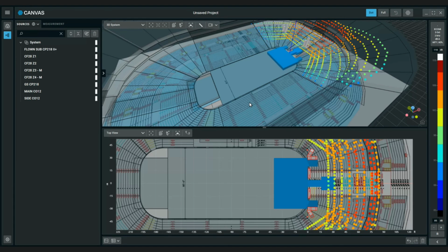The production elements and sources files, when exported, retain their offset to the 000 point of the venue file where they originated. In this case, our source file placed the downstage edge at the x=0 position, so all of our imported sources and production files will maintain their relationship to this point. However, you can see in our new venue model, the x=0 reference is the dasher board opposite the stage, and we now need to align the venue, sources, and production.